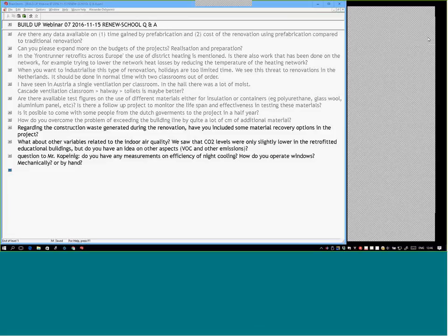Here are two points to make. In retrofits, usually these are old buildings, so the initial emission from the building materials would be long gone. So the main source of pollutants would be the children and whatever pollutants they bring, generated by their activities, and teachers also.